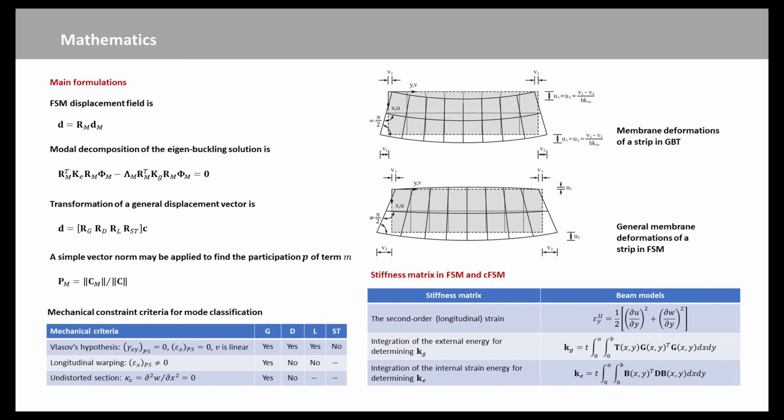The ability to quantitatively define the participation in a given deformation space provides a unique measure of coupling amongst the deformations if the deformations are coincident with buckling modes. Then the participations are a direct measure of the degree of coupling in the given instability.